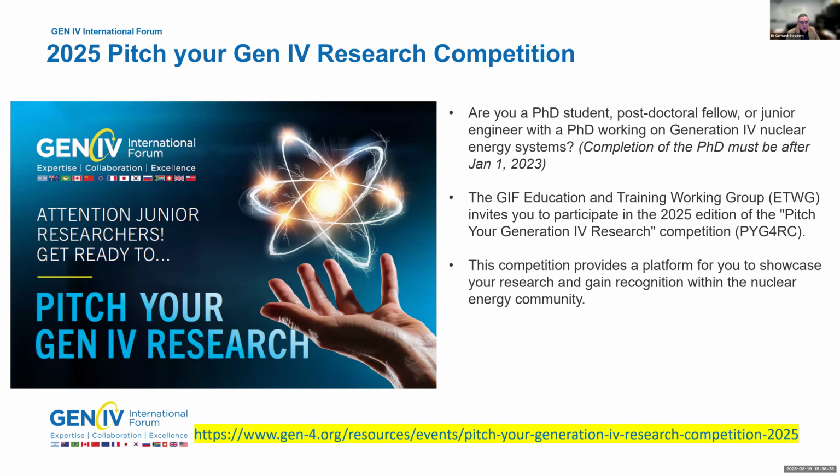It is mainly a materials challenge. It's not a reactor challenge, right? It's really, do we have the materials qualified and tested and even taken into the ASME codes, right? For example, in the US, you cannot use a material in a design if it's not certified, codified by ASME. So not only do you need the data, but it needs to be actually taken up into the code itself. So you're right, it is material challenges, metallics specifically, that's keeping us from rising really high. But as I mentioned in my slide, if you want to use refractory metals for space applications, you can do that. It's just much more expensive.